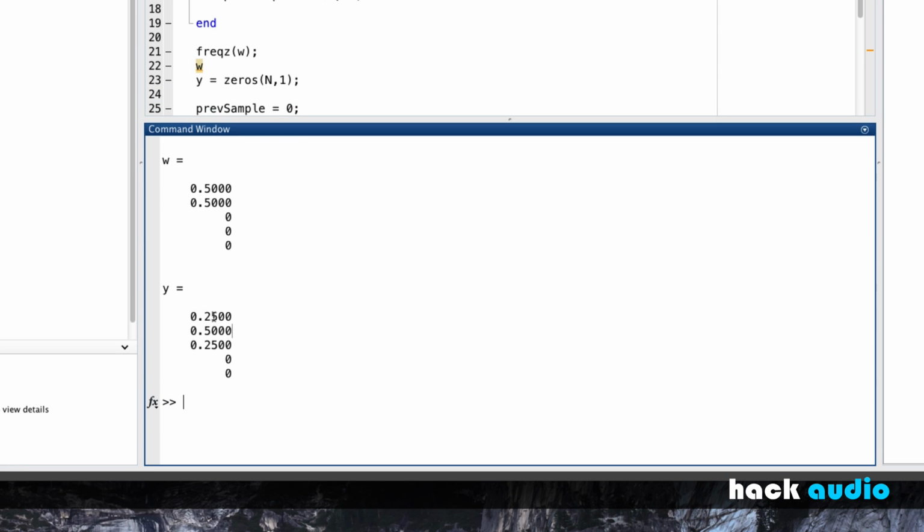So we've got one sample of delay, two samples of delay, and three samples of delay. So we have stepped it up from just having the current sample combined with the previous sample to now we're going to take the current sample and combine it with the previous sample and also 2 samples of delay. So if we want to create sharper filters, one thing we've got to do is make use of additional samples of delay. And what that's called is the filter order. What we've done is increase the order from having 1 sample of delay here to now we're using 1 and 2 samples of delay. And that's going to be an important part about creating more sophisticated kinds of filters, increasing the filter order.